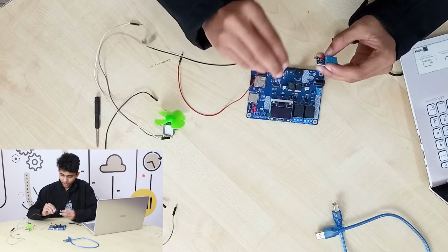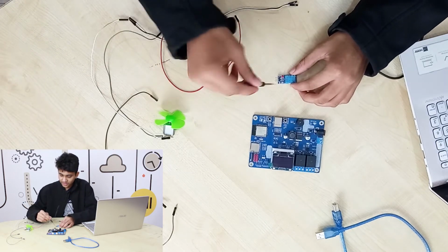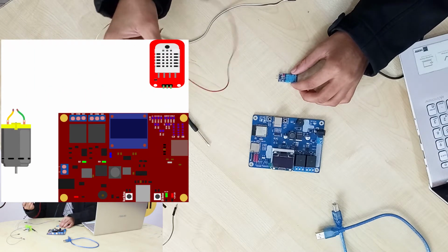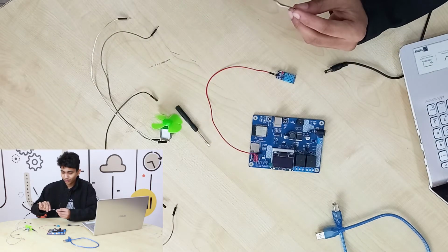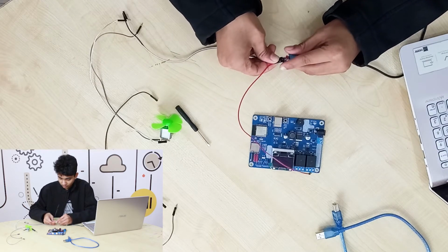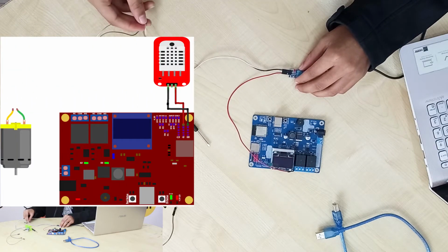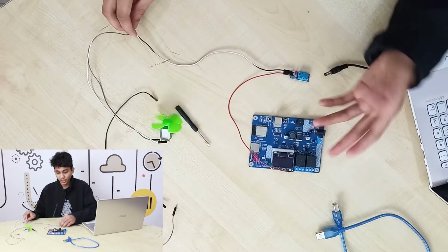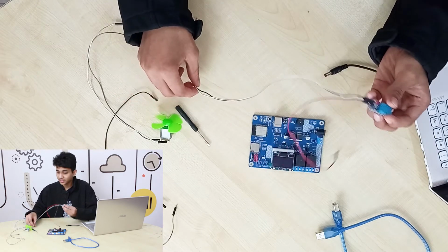There are 3 pins here, as you can see: VCC, data, and ground, GND. We're going to connect our VCC with red, as the convention goes. Positive is always red and negative is black. The white one is for data, and what the data pin does is it sends the sensor's data to our School of IoT board, so we can see the temperature and such. So this connection is done.